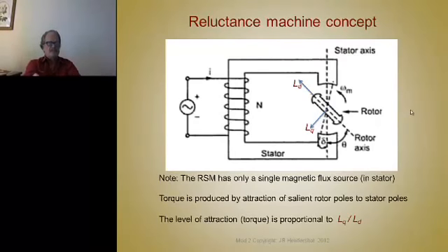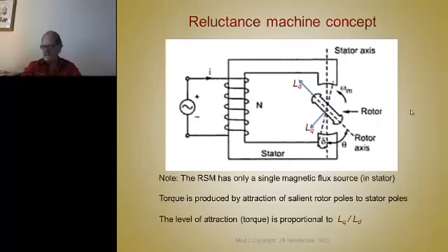Now, a reluctance machine works differently than the brushless or the induction, because it has saliency. What does saliency mean? Let's talk about that for a minute. We're back to our transformer core here with a coil wrapped around part of it. In this core we cut a section out, and we mount that piece we cut out on bearings with a shaft, so it allows it to rotate like that, you see.